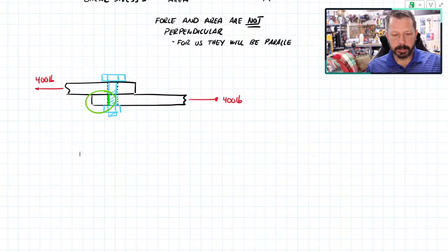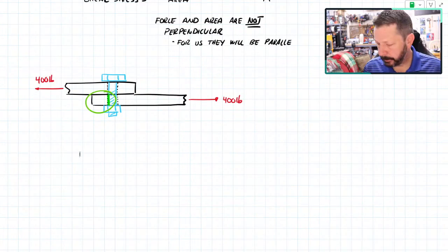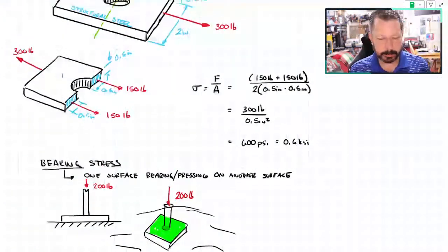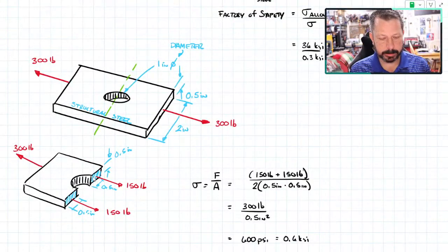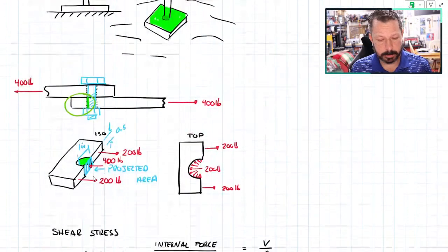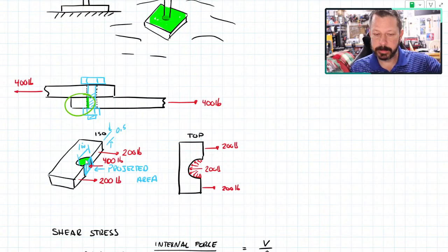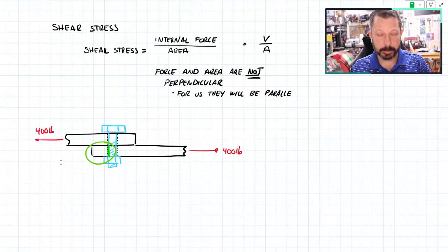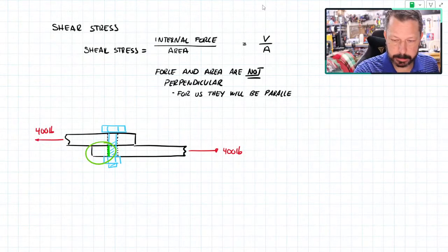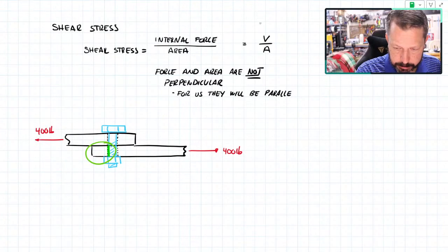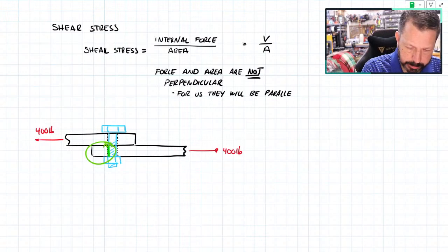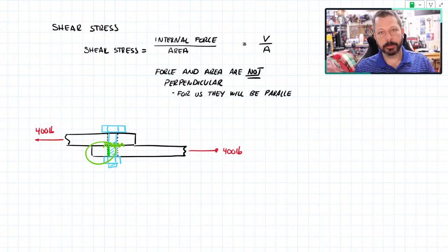Okay, so we've done 2 modes of failure, right? We did a plate that had a hole in it. We calculated how that might fail. We did maybe the bearing stress on this hole gets too large and it deforms the hole, and so now the joint is loose and wobbly. That could be a failure mode. If neither of those happen, another thing that could happen is it could just break right here. Like the bolt could break.